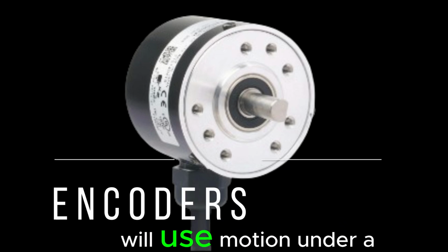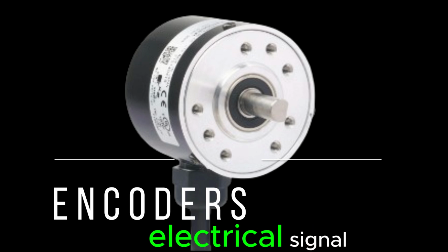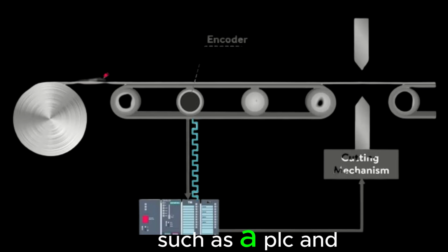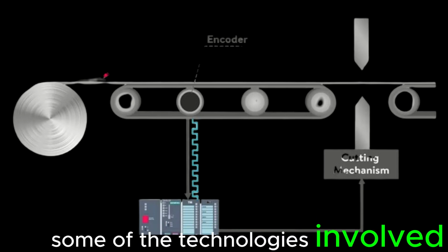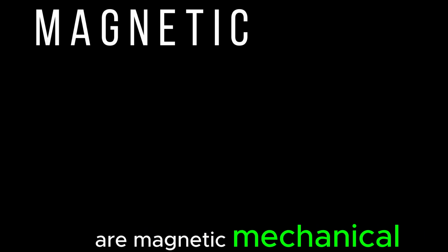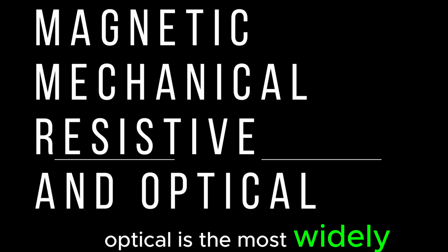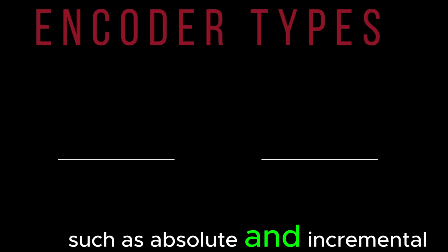Encoders will use motion under a variety of technologies and translate it into an electrical signal. That signal is then sent back to a controlling device such as a PLC and is interpreted, meaning scaled, to represent a value that will then be used within the program. Some of the technologies involved in encoders are magnetic, mechanical, resistive, and optical. Optical is the most widely used encoder motion translating technology. There are different types of encoders such as absolute and incremental.